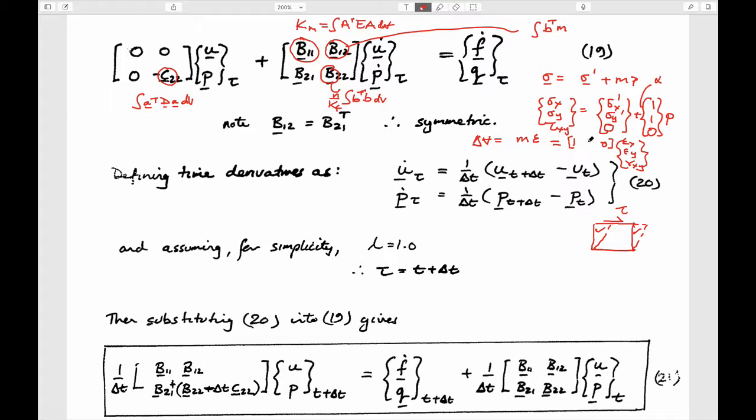this is 1. And then the volume change is due to how much it shortens in this direction, how much it shortens in this direction, but if you shear it, there is no volume change, and so there are no pore pressures that come out of this. So there's a certain, if you like, symmetry between this 0 here and this 0 here in terms of what they mean. Shear stresses are only defined as total stresses, they don't exist as effective stresses, and shear stresses cause no volume change, and the two issues are somewhat related.